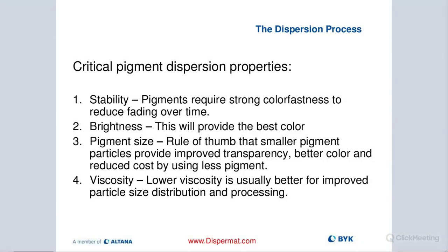If it's too low, then we're going to have a difficult time putting in the right amount of energy to break up these particles and binding forces. So ideally, we want to look at something like 1,000 centipoise to about 3,000, which is really optimum for a proper pre-dispersion.